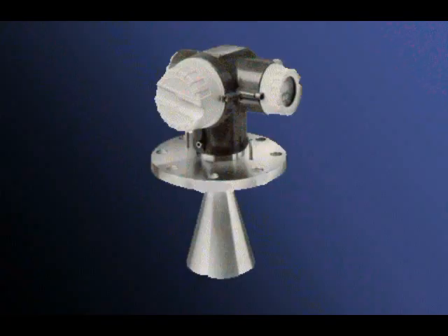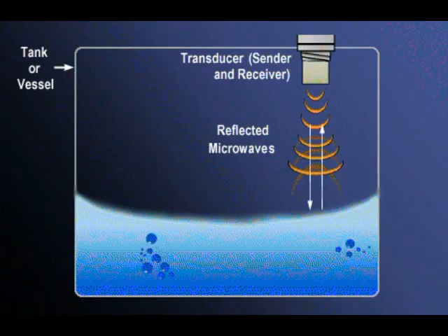Microwave technology is used in turbulent, high-temperature, or aggressive material. Microwave technology is similar to ultrasonic devices in that both employ a type of wave technology. In the case of microwaves, at permissible levels, microwaves are bounced off the process material and received by the same transmitter. Output is scaled to a DC signal in the range of 4 to 20 milliamps.